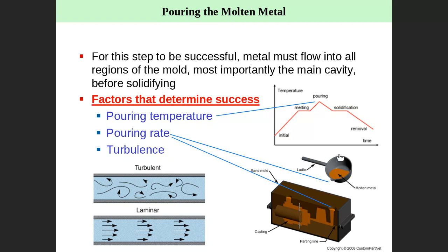The liquid you pour into the mold must be at a proper pouring rate, must be not very slow and actually not very high also as well. Why? Just drop quickly and put all liquid very quickly. If the rate is very slow, then you get premature solidification.